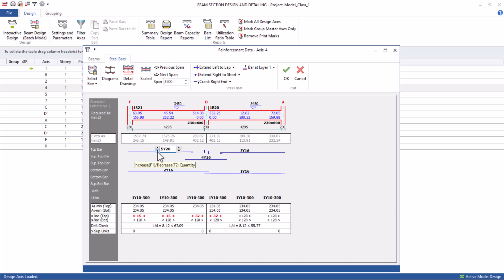Now we can go ahead and create another option, which is creating a second layer of bar. So if we come here, you can see supporting top bar. This is our main top bar, and we have a space for supporting top bar here. So if we come under this place and click for this supporting top bar, you see if I click this, I can increase this capacity. Now this is calculating this with this one. It is adding both of them together.